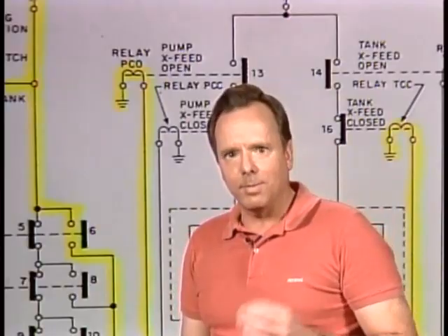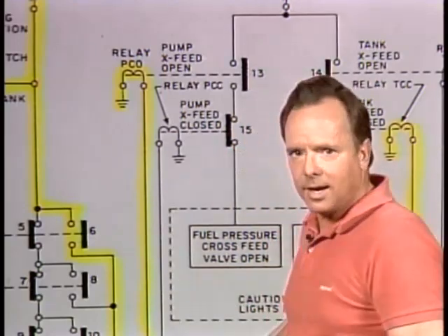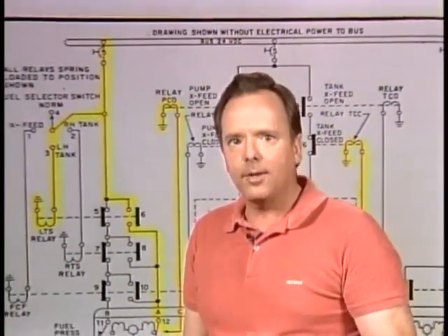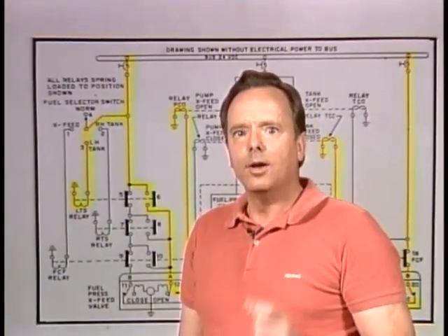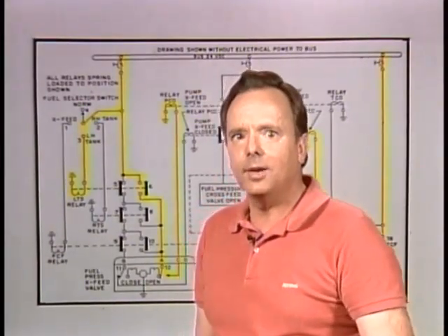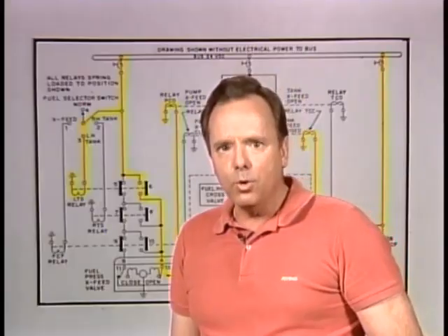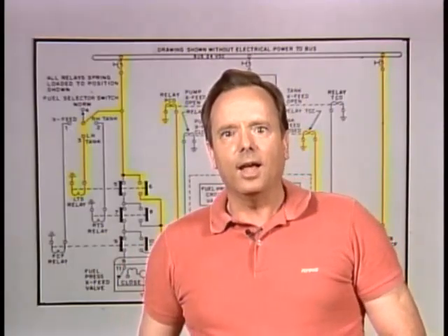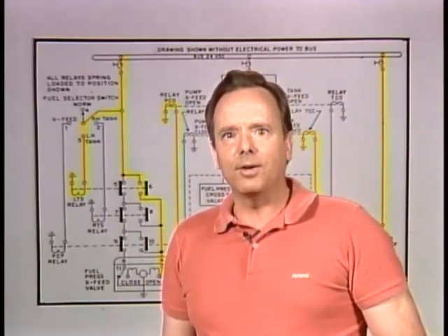Now, the real reason we include 15 in the answer is the FAA has it in all of their answers that make sense, so we know they expected that switch to operate for just a split second there. So the answer to this question is, if you select the fuel tank position of the left-hand position, turn on the power, switches 5 and 6, they operate together, 11 and 12, they operate together, 13, 16, and 15 will all become moved or energized or activated, and 15 is only activated very briefly.